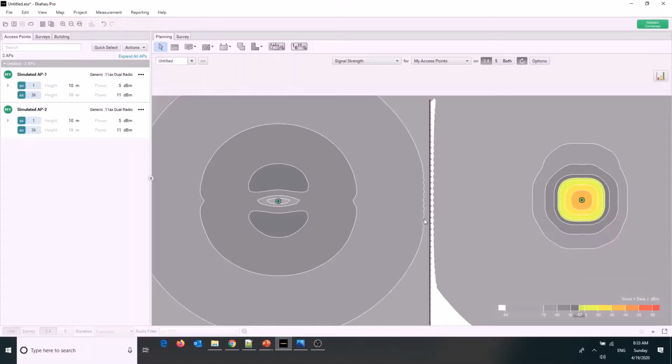That got reduced also. Let's try to click on the same location. You see the difference? This mobile device is able to receive the same RF signal in the same location, from the same distance from the access point, at a different signal strength value. So this is something you don't have control over. It's about the manufacturer, the manufacturing process of the antenna itself inside each device.